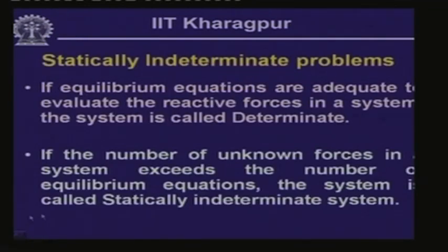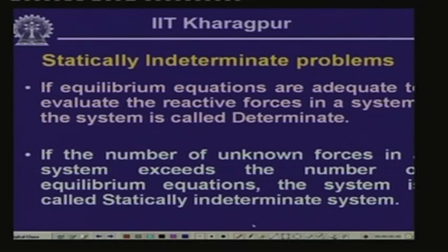Now, let us look into the important aspects which we do come across in many problems related to different fields, which we designate as a statically indeterminate problem. Now, when we talk about a statically indeterminate problem, naturally we will have to first know what we really mean by a determinate system. We have seen earlier that we have three sets of equilibrium equations in statics. There is summation of horizontal forces as 0, summation of vertical forces as 0, summation of moments as 0. These are the equations of equilibrium.